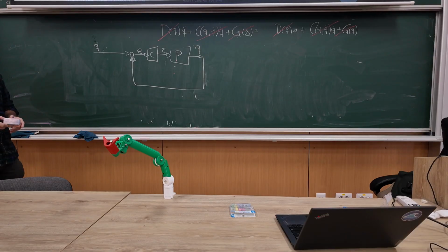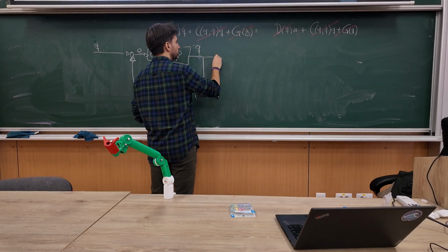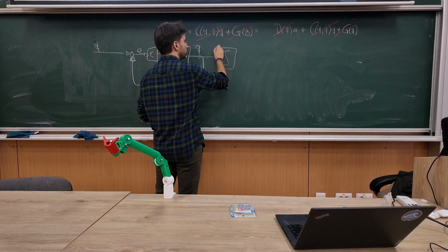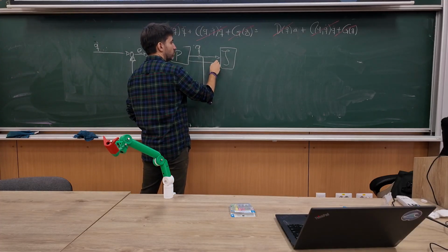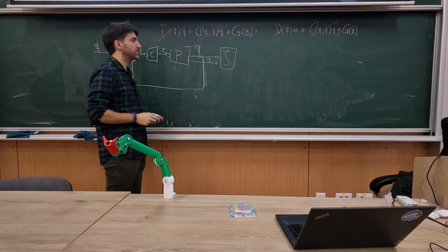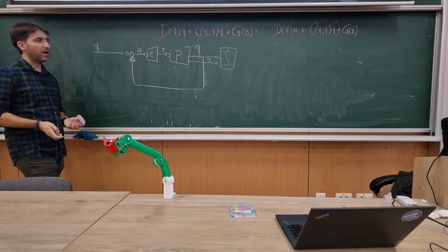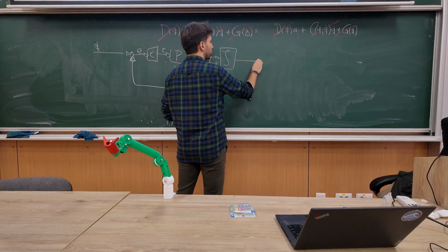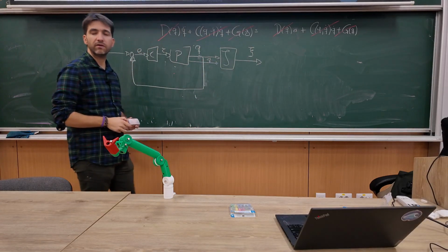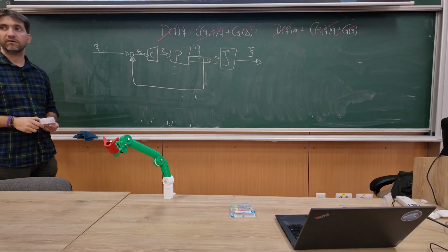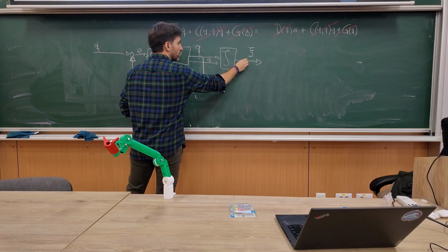After the ADN, here, because we have the position and the velocity. I can measure the velocity, let's say. And what do I get from this? I get the end effector velocity. Okay, but how do I control it? We can use the inverse Jacobian. Okay, so this would be our feedback, you said, right?